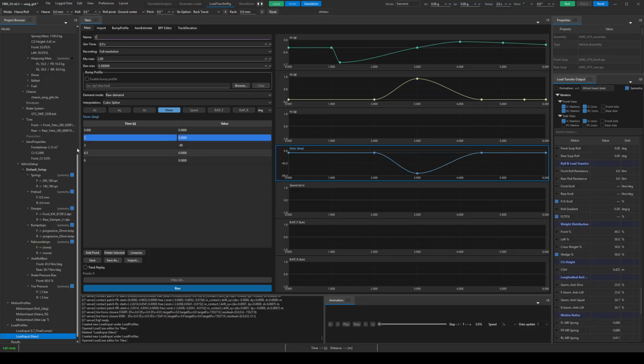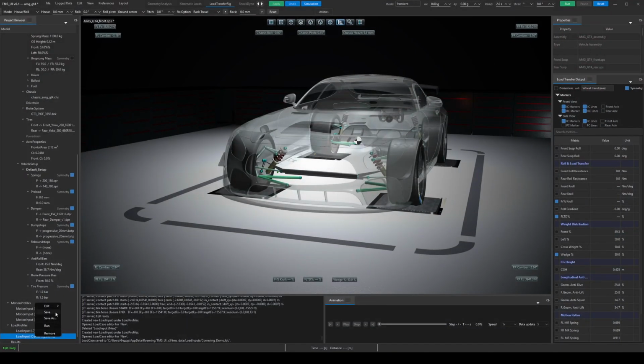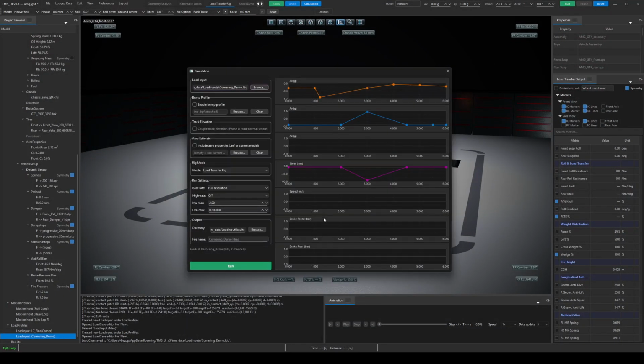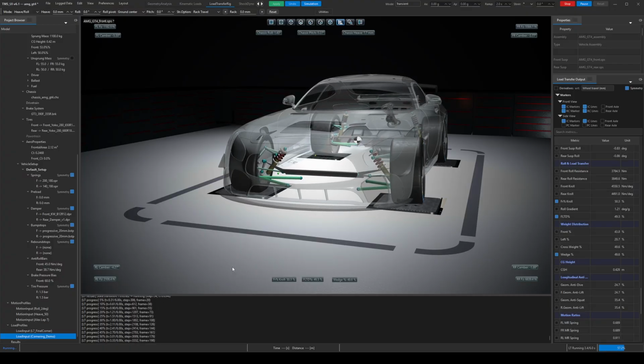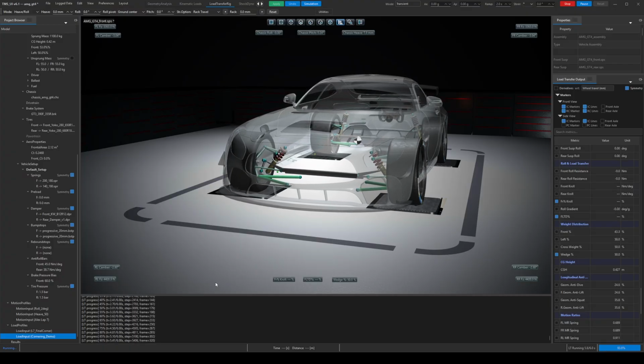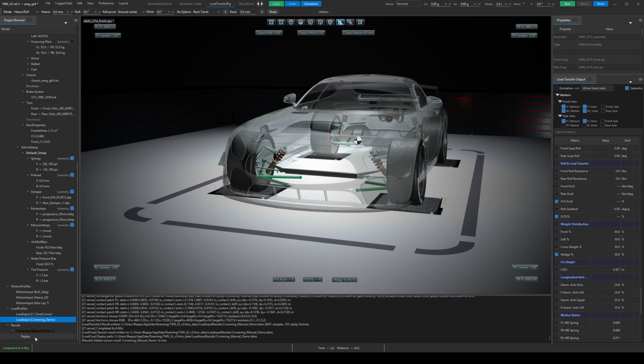The load input then appears in the project tree. From there, the user opens the simulation dialog, chooses the result file name and destination directory, sets the logging frequency, and runs the simulation. The run is animated in the main graphics window, which gives a useful first sanity check. Visual inspection is still a good first-pass filter, because it helps confirm that the model is behaving sensibly before going into detailed plots. After the run, the results file is added to the project tree.